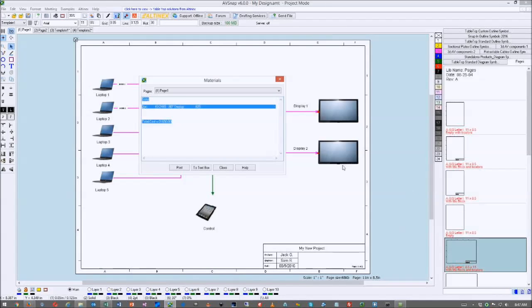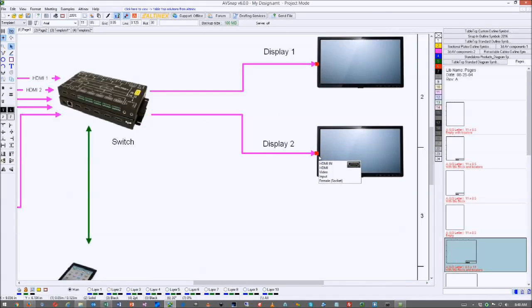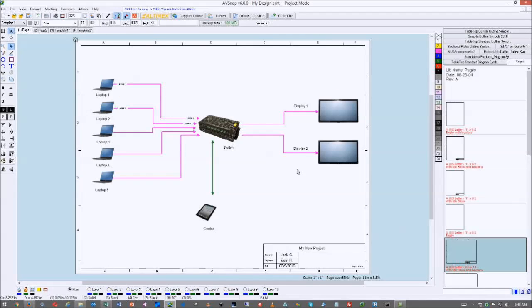Okay. One of the questions is, when we save it as a PDF, do the mouse over notes show? No, when you save it to PDF, it only shows what you see here. So you see there are snap points here. A lot of times when you save it to PDF, you don't want to see snap points. So there is a shortcut called S, which removes the snap points. So now it's nice and clean for presentation.